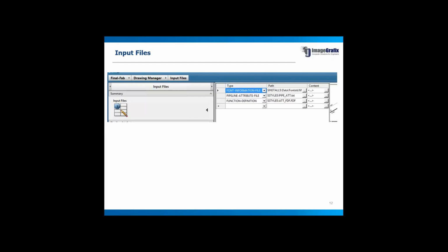For example, 901, 902, 903: 901 is assigned for spec, 902 is assigned for your design pressure, and 903 is defined for your design temperature. So if that is the case, in your function definition also the same sequence has to be followed with the numbers.